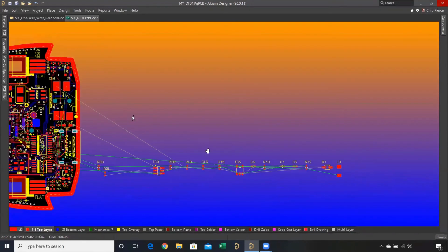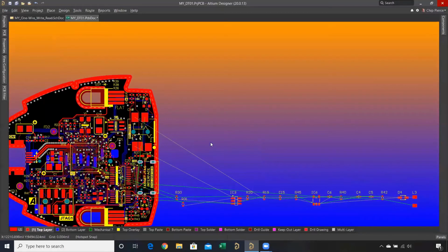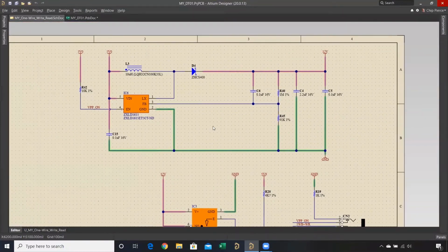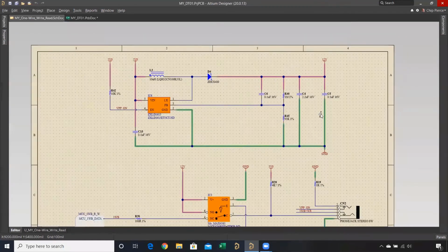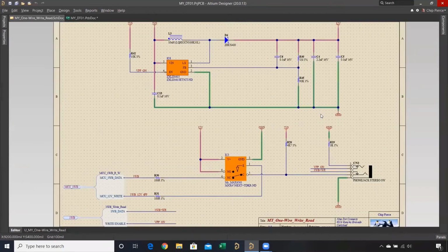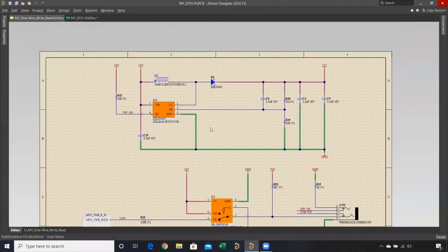All right, so let's take a look at some of these helpful component placement tools. Back in the schematic, I'm going to show you what's called cross probe and how to use this cross select mode. For example, if I wanted to keep all of these parts up here near the top of the schematic, I'm just going to hit VD to fit the whole document and VF to fit all objects and pan down.